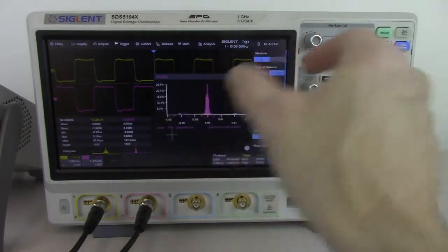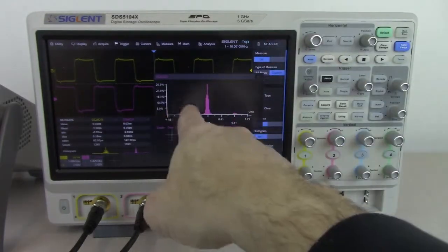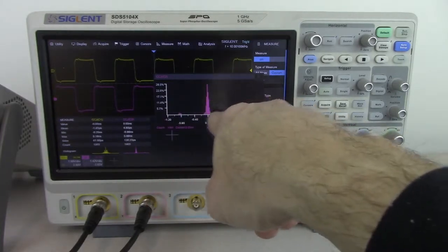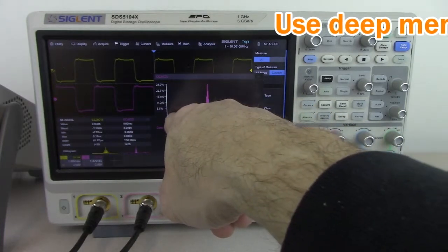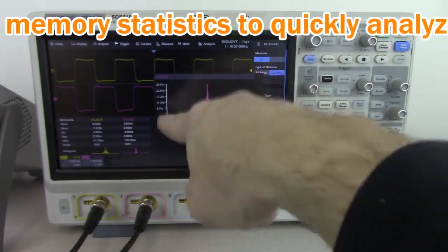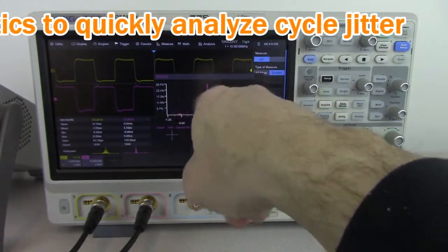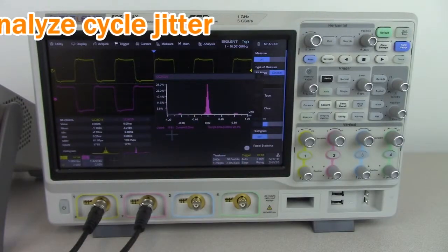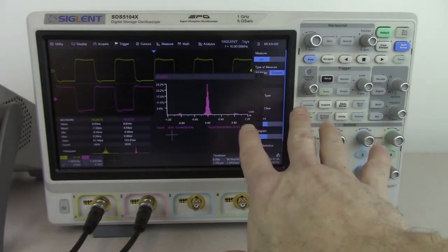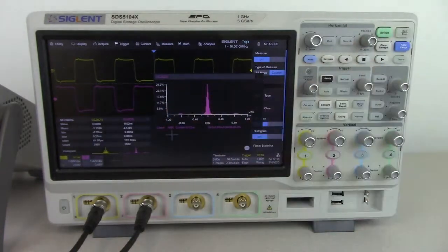Basically, the jitter is quantized, and that's very easy to see as we start to collect those statistics. Every once in a while, we're getting a bin over here with the jitter or the rise time, and then we get the rise time here. So the cycle time, the jitter, is actually fluctuating between these two. Very, very easy way to take a quick look. We'll let the clock run for a period of time, and then we can see, does the clock have some kind of deterministic or quantized jitter?